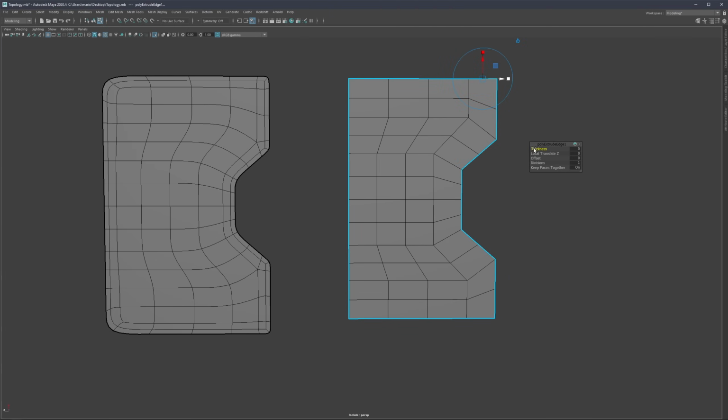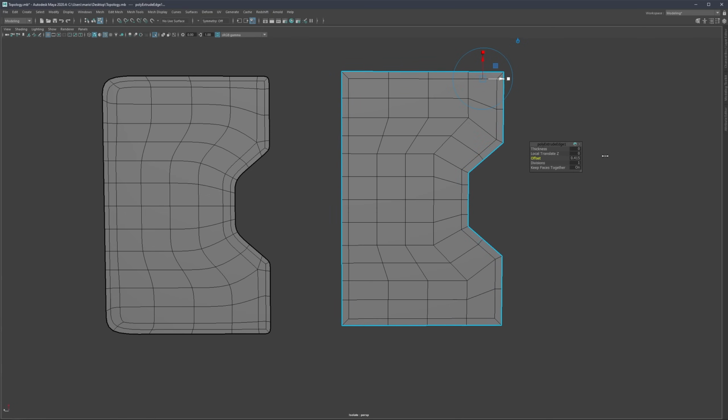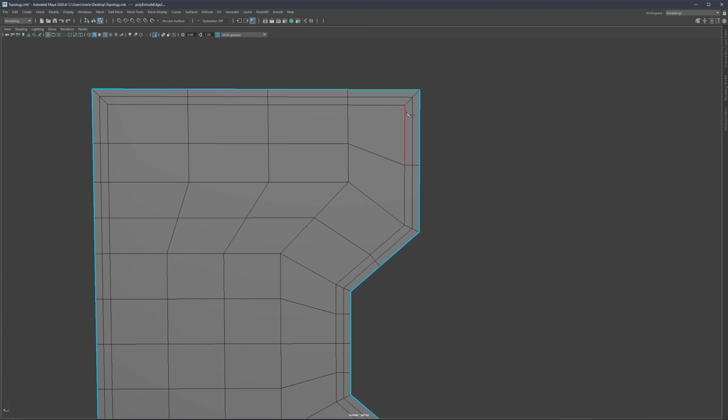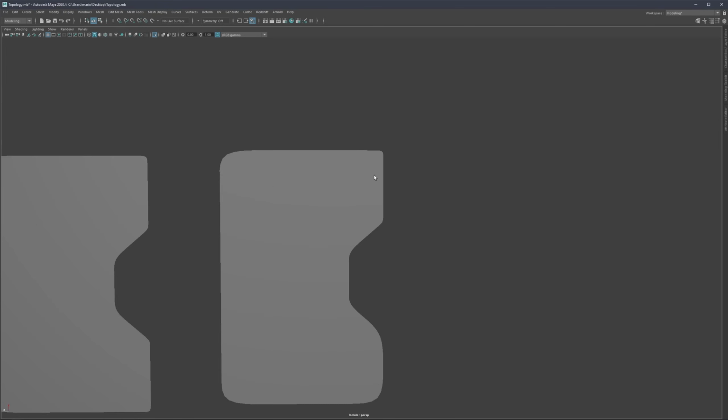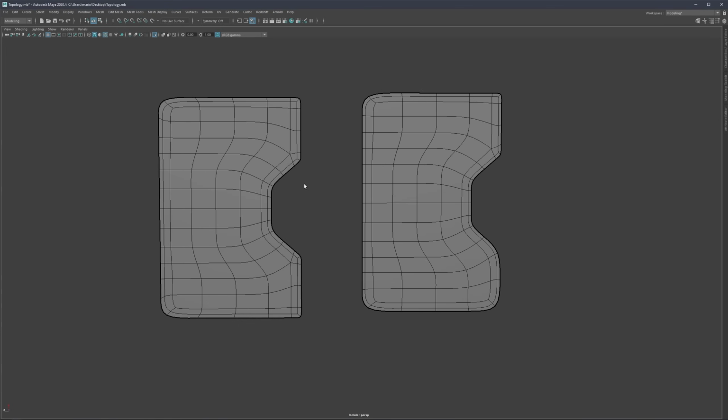So the way to do that, again, is going to be through the support loops. So again, if we offset this 2 more times, we're going to have more control on the top of what to actually do with these corners. And then we just remove. So this is, again, depending on what you want. So if this is something that we would need to sharpen, then we would do it like that